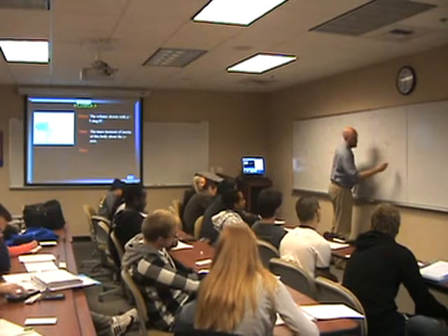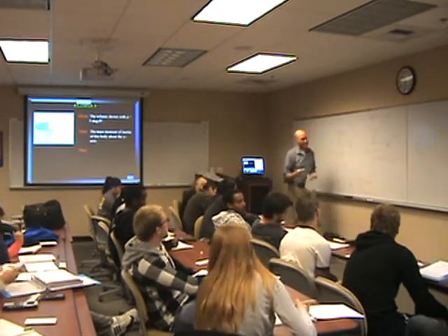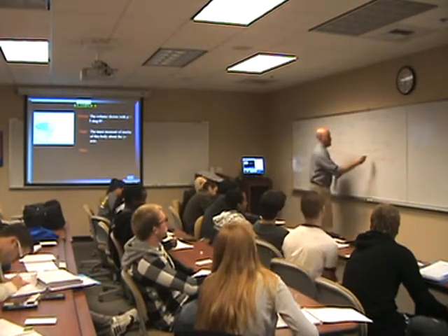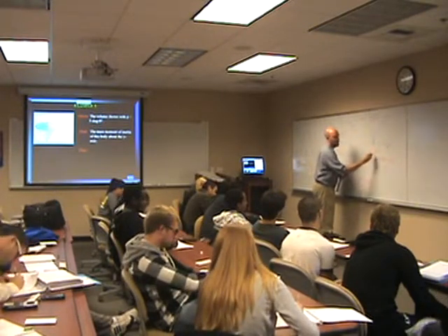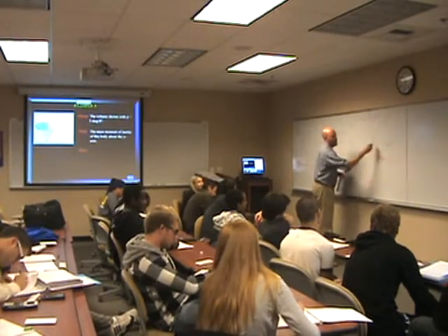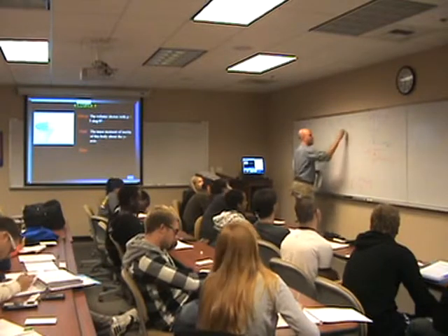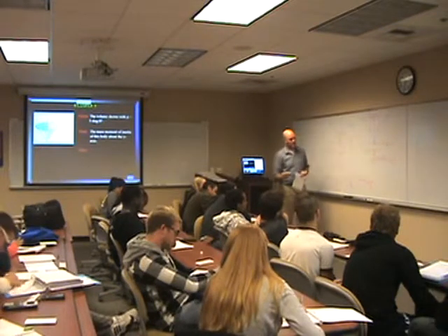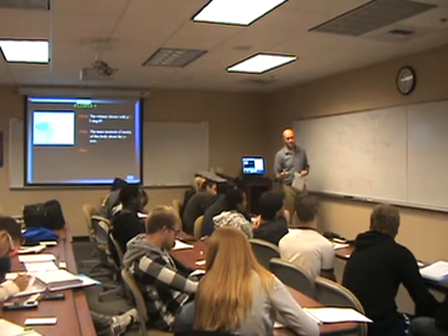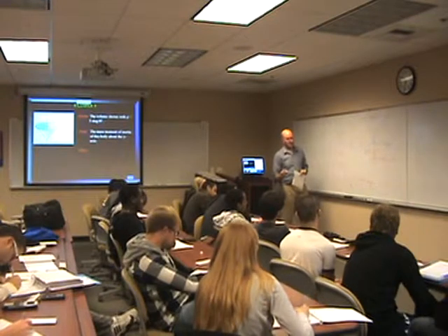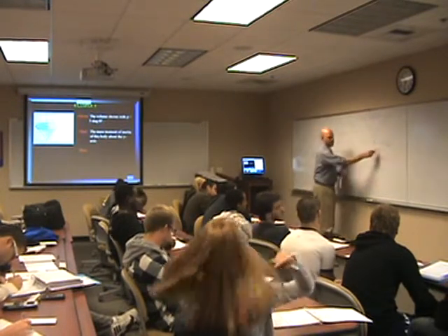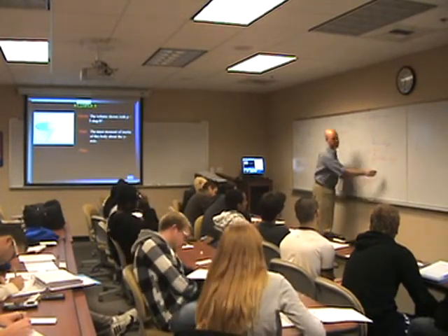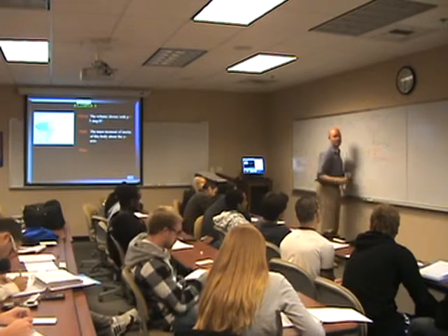So this here is your mass times your radius squared. Now we've got to get rid of that y. We need to integrate this from 0 to 1. Again, now we're integrating this way, where before we integrated that way. Why do we need to multiply by 2? It's just m r squared. But now we need to substitute. Now it's dx, so we need to write y in terms of x.